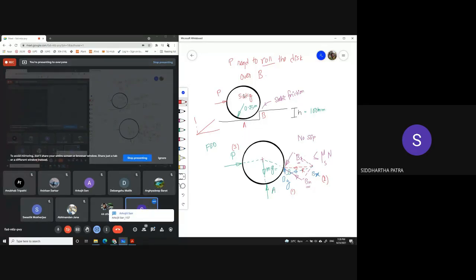I would not be calling it supporting its weight. I mean, there is a combined effect of P and the forces at B and the weight, all of which A is supporting. That means A is simply balancing all of them out. It's still an equilibrium problem. It's just that the moment the reaction from A becomes 0 is what we are concerned with.